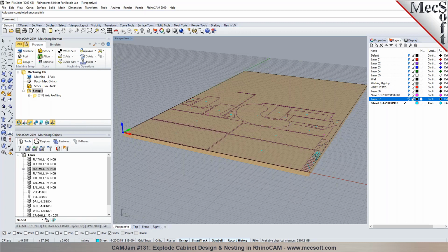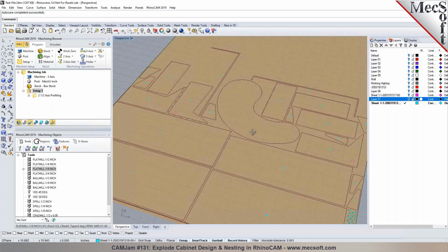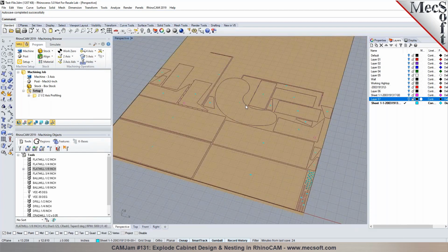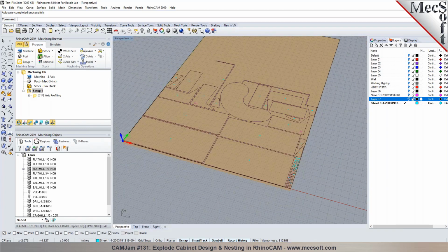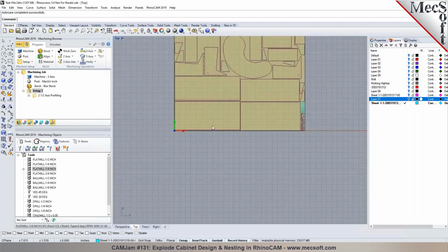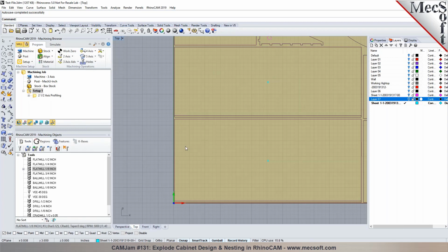Yeah, so it'll automatically place numbers, we call it annotation, and it'll have a number for each part. Now, if you want custom numbering placed in certain locations, you can actually use Rhino to number these parts, and then when you nest them, you select the numbers as well in addition to the part you're trying to nest. So that'll nest it with the numbers that you have defined.